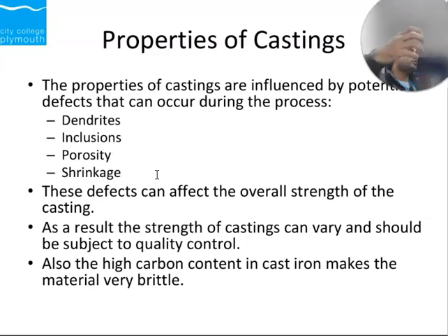Porosity is when you're pouring too quickly and the air bubbles might get entrapped. This is why we use ultrasonic vibrators, which vibrate and get rid of all the air bubbles and all the porosity. When I talk about porosity, they are very tiny, teeny air bubbles, micro voids or voids.